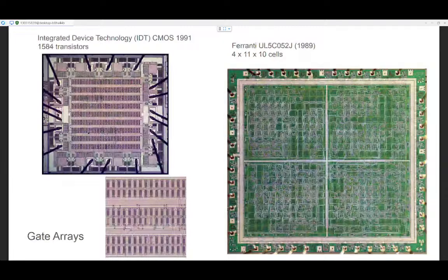And the gate array is possible because there are several universal gates. For example, the NAND gate or the NOR gate, that you can design everything using just that single gate, multiple copies of that single gate. For example, the very first integrated circuit that was used at a large scale was a chip that had 2 NOR gates, each one with 3 inputs. And that was used in the Apollo guidance computer that landed on the moon. And they had thousands and thousands of the exact same chip, 2 NOR gates. Then you just wired them, and you made the Apollo guidance computer out of 3 input NOR gates. You don't need anything else.